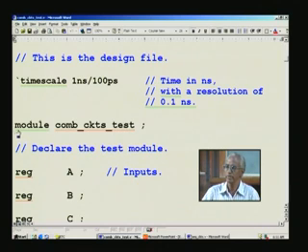Here you declare module, with a space, and then give the actual module name, which happens to be the test bench. You give the full name, and notice that .v is not to be given here. If you give .v, I think the compiler will complain.